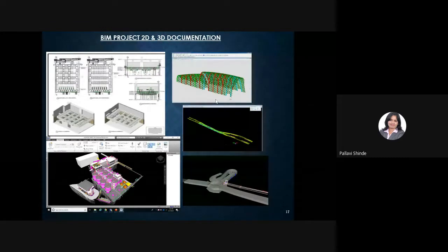So all of that is a part of BIM project delivery, which is applied for both 2D as well as 3D documentation. All of this will lead you to a successful BIM project life cycle if you understand it right from the start: how the project starts from the BIM execution plan, how the model is developed at different LODs, how to start with concept, then go to schematic and detailed design, then apply the annotations like object properties, then extract bills of quantities wherever you require.